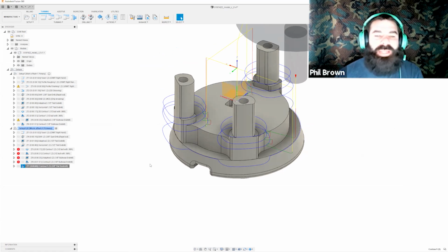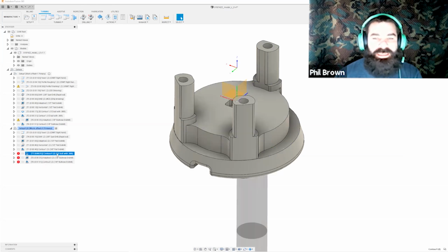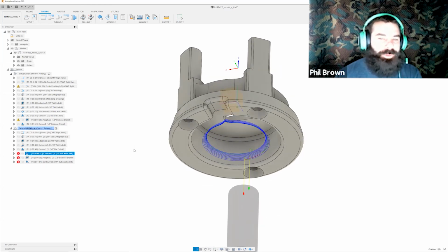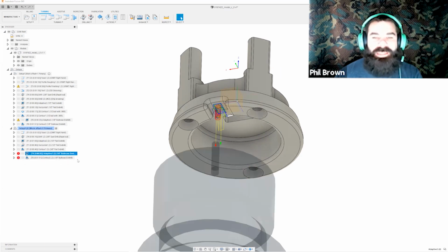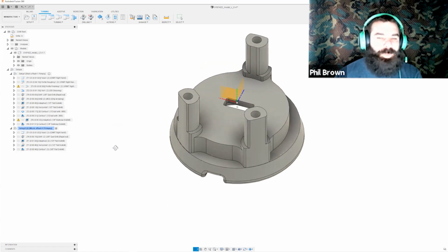I actually added some time on my machining and am able to go around all those features. Another thing I can do is drag and drop this program up and continue down with what I'm doing. The 2D contour is no longer needed because I did clean up my walls and my floors. The last thing here is another contour toolpath for a 3D feature I don't need. And stepping down a little further, I'm not using that smaller end mill anywhere on those parts.